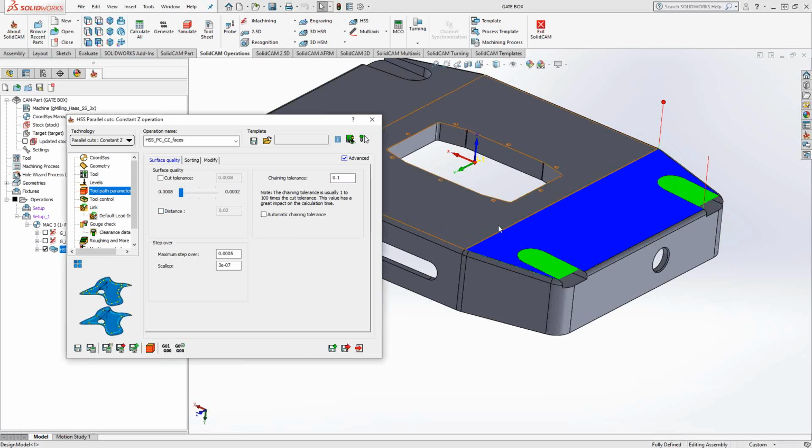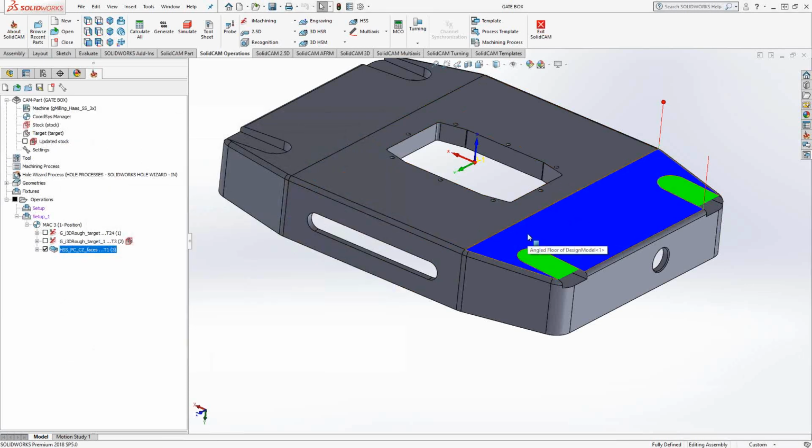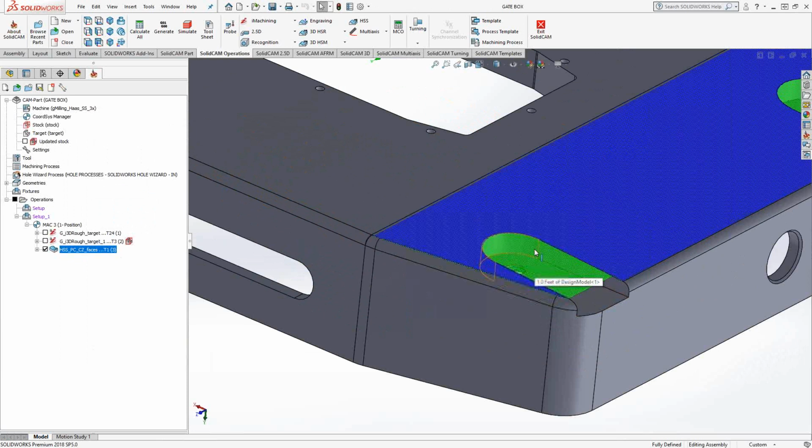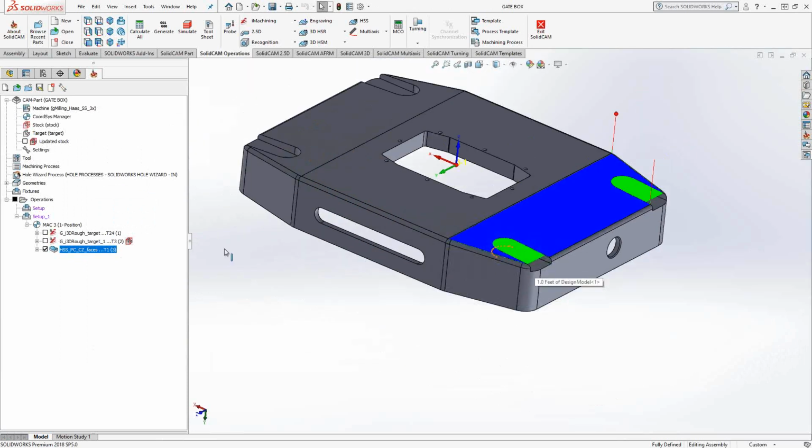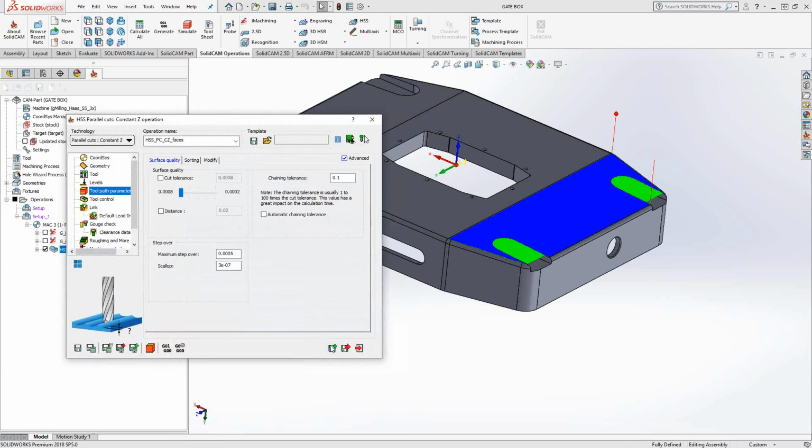Now, I only did that one surface for a reason, because those controls over gaps along the cut, link between slices, if I had chosen both surfaces in the one toolpath, then this gap between them would be considered a gap along the cut. So I wouldn't have the same control I had here where I could say follow surfaces. So in that case, if I want to do the other side and still maintain that smooth toolpath, that good look to it, I'm just going to do a save and copy.